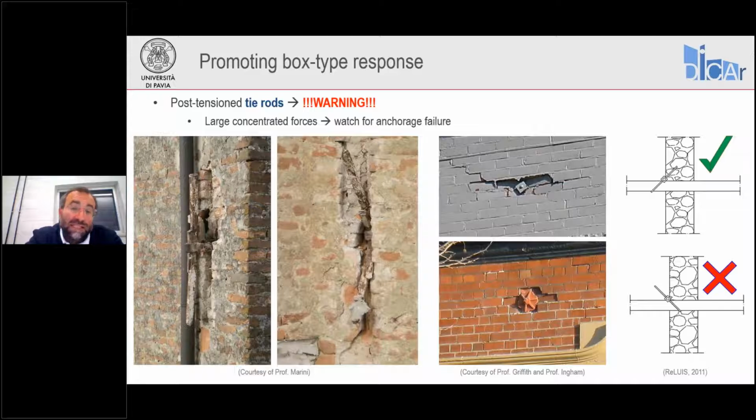You see, in this case, the anchor system bent, basically, while the rod was pulling in. On the other side of the wall, you see the anchorage, which is extending outside. It's not bearing against the masonry anymore, because that rod is basically shifted all the way to one side, and it has completely lost its effectiveness.